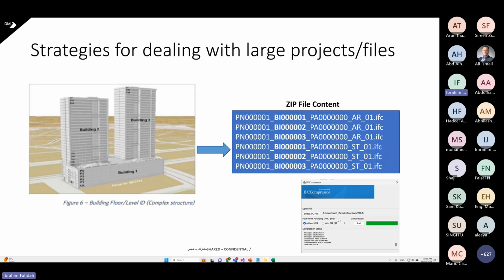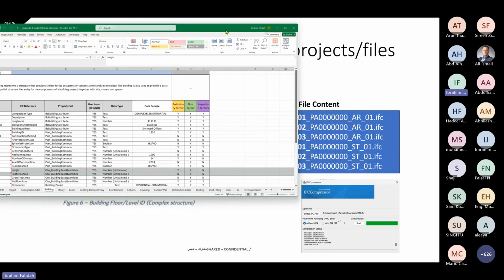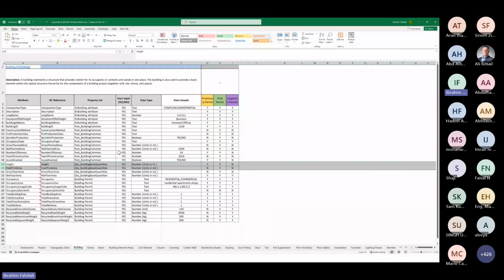The other things maybe quickly also to highlight, it's useful. So in the standard, I think just quickly to say, I have a few questions on the team saying, what is the information required to submit with the BIM model? Arun highlighted that when you fill in the information in your Revit model or the BIM model, if you're using other authoring tools, you need to always refer to this file, the attribute matrix, and in there you'll find different objects that are required for the permitting purpose.